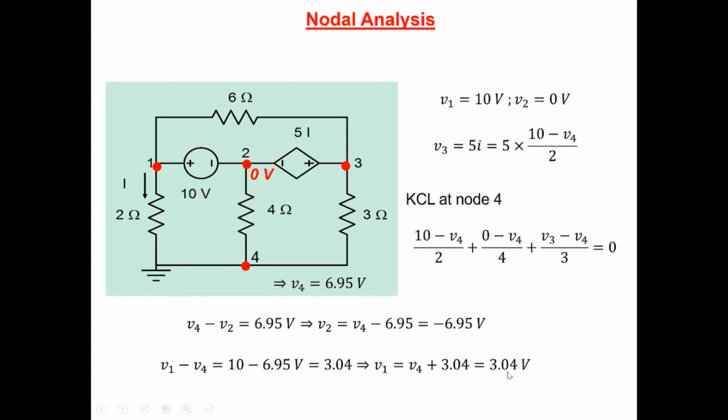So what this is saying is, even if a ground connection is given and you're not happy with this ground connection from the analysis point of view, temporarily you can forget about this ground and assign a reference node the way you want, the one which will help you in analysis. Do all the analysis, and you'll get all the voltages with respect to node 2. Then you can transform it back to whichever reference was used earlier. So this is what we did here.